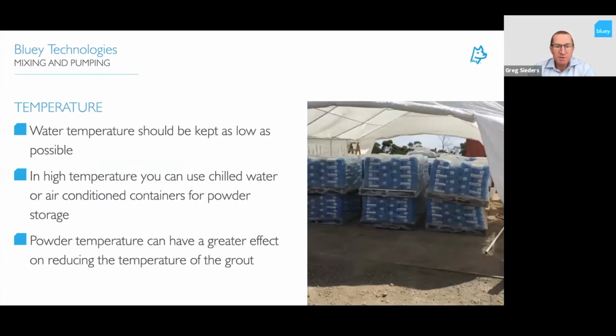So water temperature should be kept as low as possible when you're mixing, so you don't cause the heat of hydration to happen quicker in your grout. In very high temperatures, you can use chilled water, or you can also air condition containers for your powder storage.